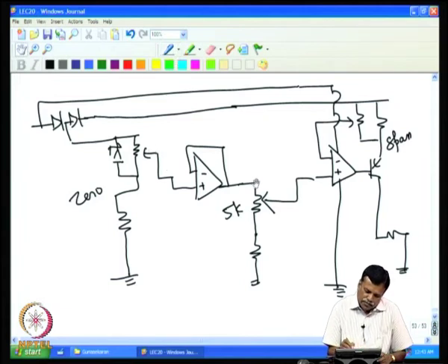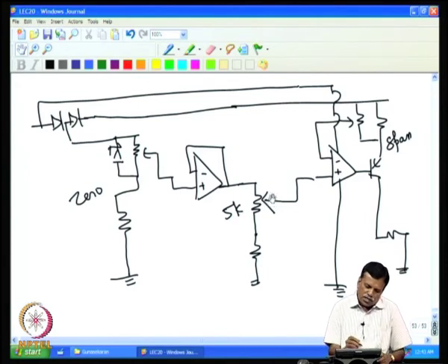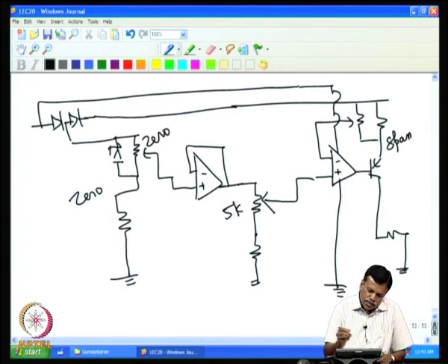So, now we have the flexibility to vary this voltage, so that we are able to adjust the 0 even if this potentiometer is not going to the one physical end. So, this gives a provision to adjust 0 and span. So, we call this a 0 pot. This is the span pot, this is the position pot.